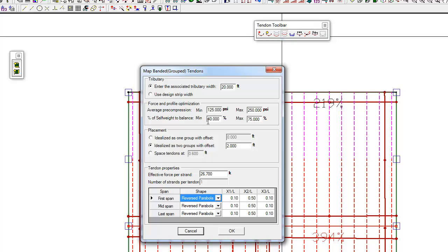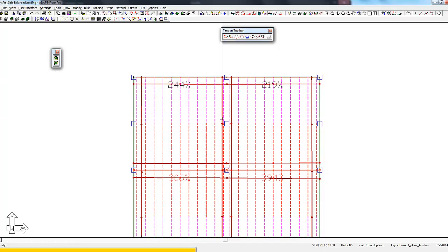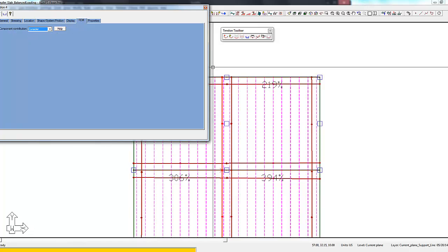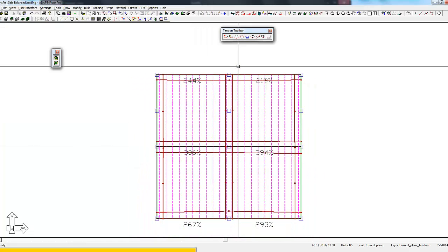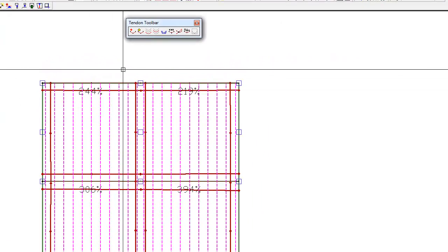If we're doing staged construction, what we can do is set one tendon line for each independent stage. So I could have maybe 5 tendons passing through this zone. Tendon 1 would be stage 1, tendon 2 would represent stage 2, and for each of these tendons we could turn those off and on using this consider and disregard. We could also turn off and on the levels above that are not being considered for that stage. So that's just a way to maintain a central model and be able to do a staged analysis within one model rather than having to maintain multiple models for the same project.